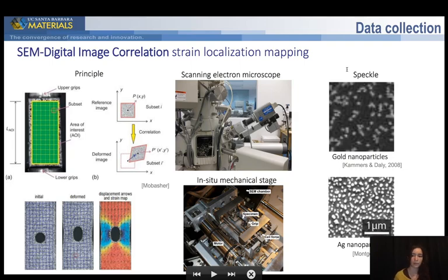So what we do practically is that we can conduct in-situ tensile experiments directly in the SEM and take DIC measurements alongside. As far as for the speckle, specific methods have been developed for depositing ultrafine speckles onto the specimen surface. They involve the deposition of nanoparticles by chemical means and surface activation, or sputtering, then etching of thin layers of specific metals onto the sample surface.